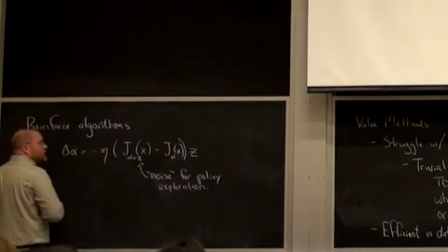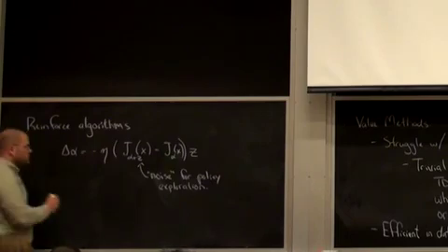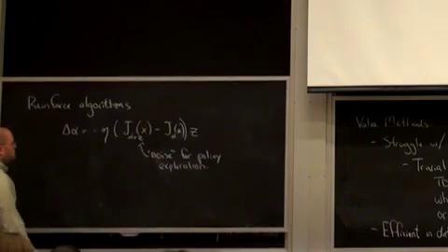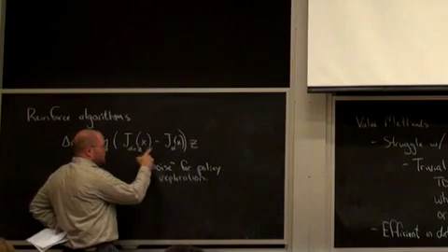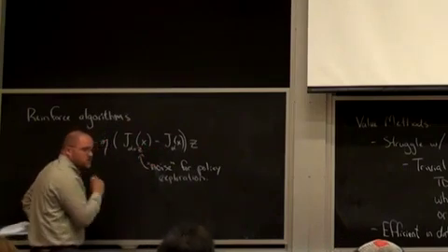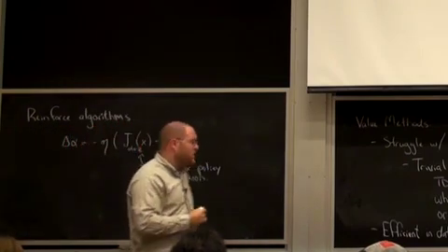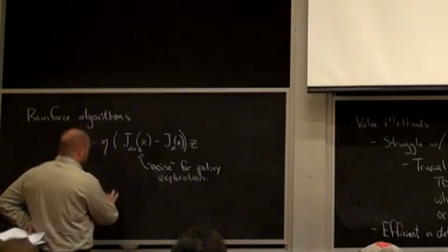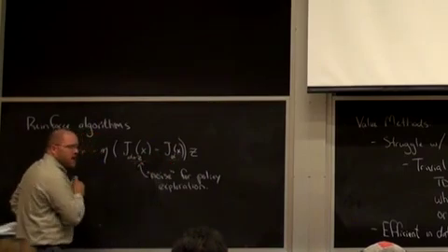And that's actually a good estimator, a reasonable estimator of the gradient. And if I multiply it by the learning rate, then I get a gradient descent type update. Okay. So this is not useful in its current form. John told you about better forms of it too, but the problem with this is that I have to run the system twice from exactly the same initial conditions. You don't want to run two trials. You don't want to simulate your robot exactly twice for every one update, and it sort of assumes that this is a deterministic update.